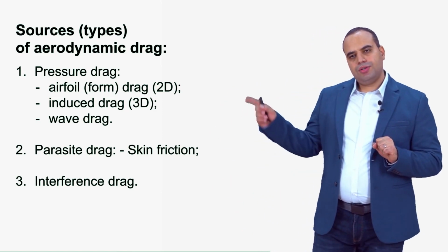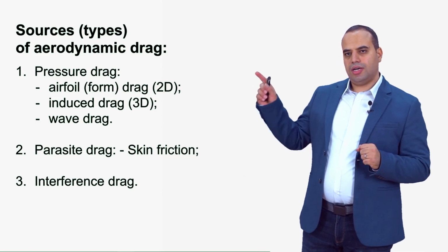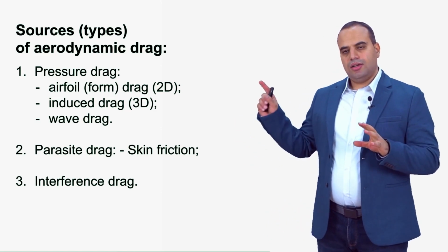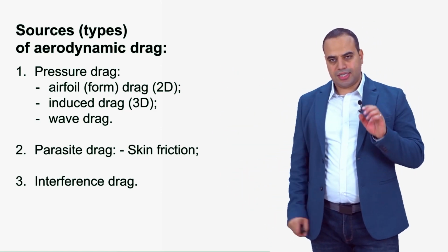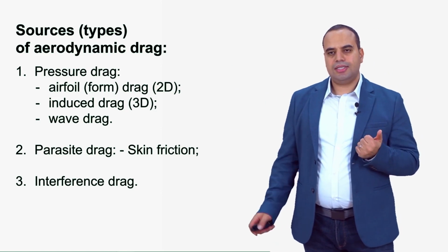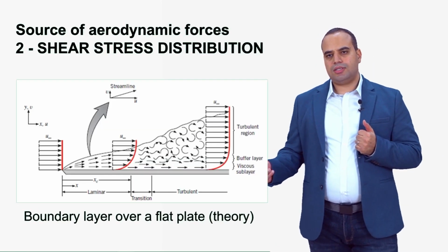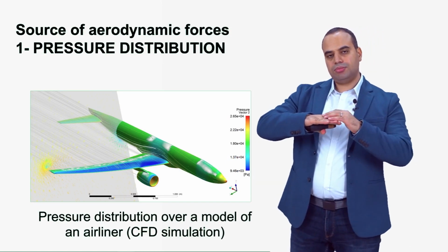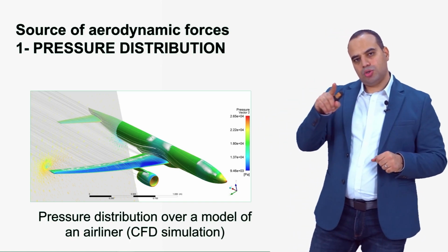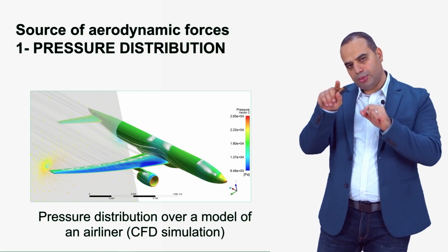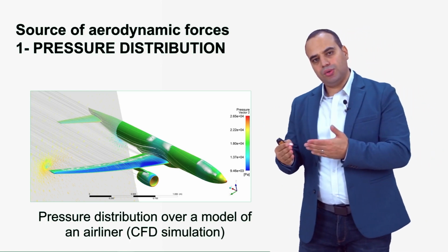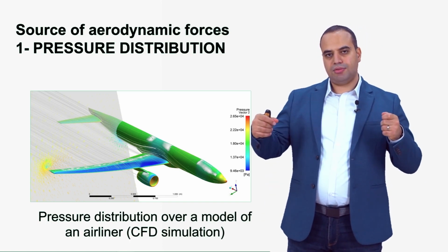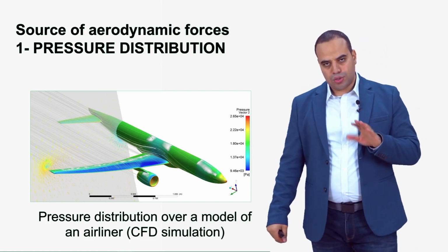Now, there are some other sources of drag as well, which have to do either with the pressure or with the shear stress distribution. Basically, apart from the skin friction, all of these have to do exactly with the pressure, right? So, for example, the induced drag has to do with the wingtip vortex in three dimensions, because the wing has a finite span, and at the tip of the wing the high pressure meets the low pressure, and this generates this kind of vortex. And because we have a vortex, the flow is accelerating at certain points around the core, and because of the acceleration of flow, according to Bernoulli's law, we have low pressure, right? And low pressure in that core is like a rope that is preventing the aircraft from moving forward, and that's called induced drag. Why is it called induced drag?